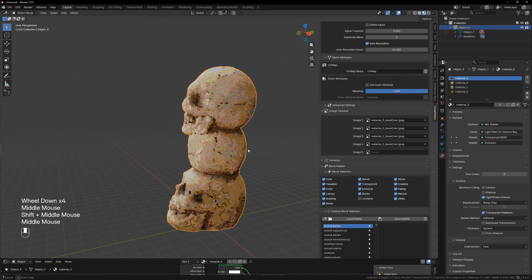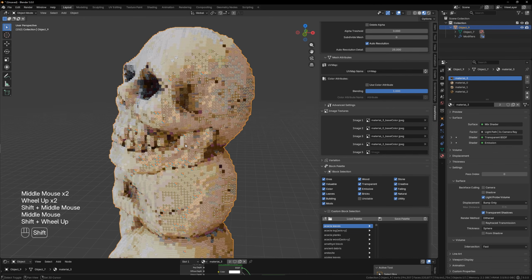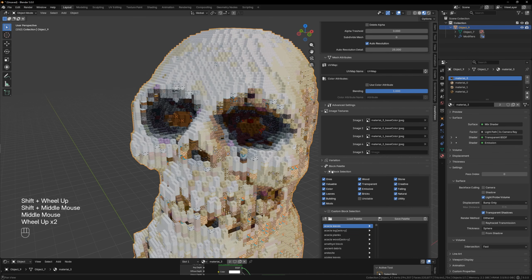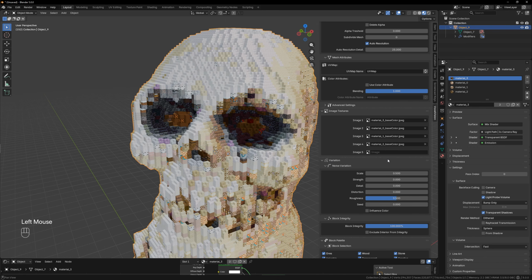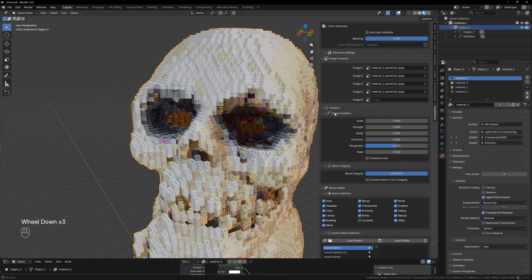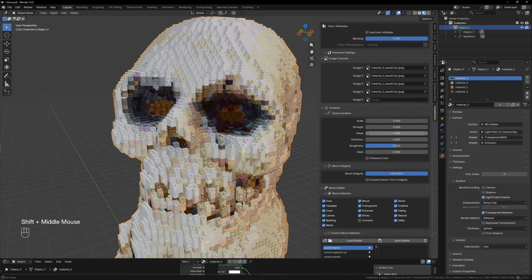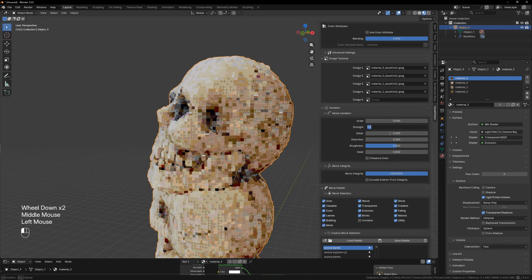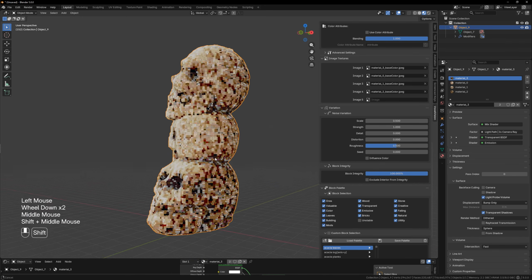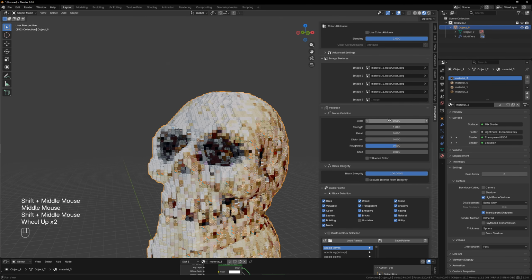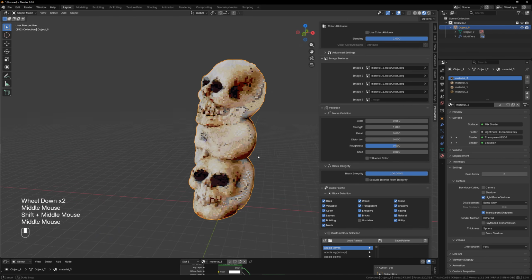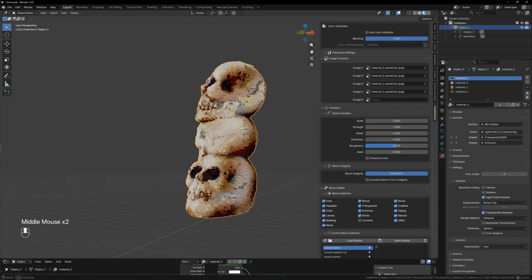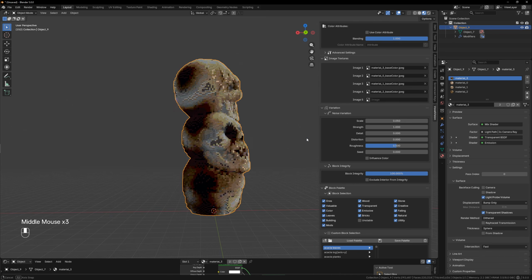In case you don't like any of those blocks or how it detects, basically maybe this is too sharp, you can introduce variation with this variation panel. In this first section we have the noise variation, which is scale, strength, detail, distortion, roughness and a seed. So if I crank up the strength to maybe 0.5 or maybe 1, you can see it gets very, very noisy. And you can then change the scales. If you change this to like 0.5, you can see we got a lot of big spots, which are actually looking pretty cool on this model.